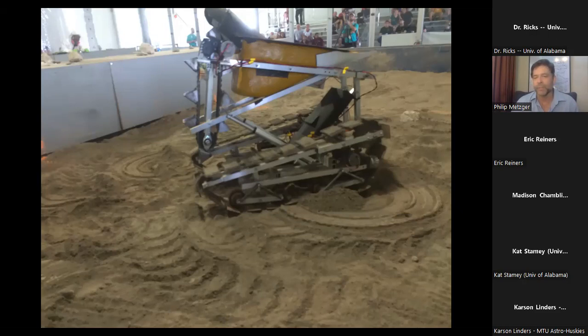But even wheel systems, if you have a system without any sort of active steering, then on a smaller scale, as you turn, it's called skid steering because you're skidding. The way you steer with that kind of system is you simply turn the wheels on one side of the vehicle at a higher rate than the two wheels on the other side. That causes one side of the vehicle to move forward faster, which rotates the vehicle. But as you're doing that, the vehicle is rotating around its center line, around its center of gravity, at the same time that it's translating forward.